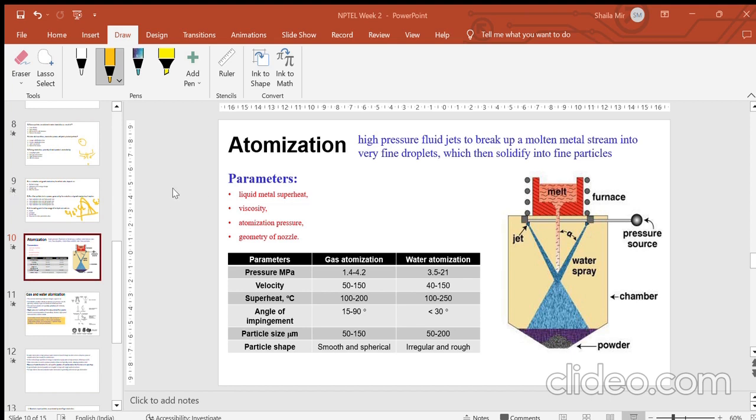And also these are some of the questions where we say that spherical shaped particles are produced by centrifugal atomization. Is it true or is it false? True. True is the right answer. Under which set of conditions is the irregular particle shape obtained?